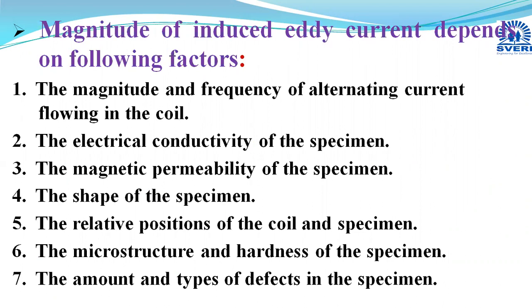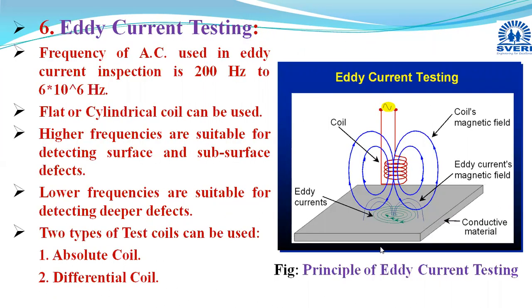You can say that impedance is nothing but the resistance provided to this eddy current. Okay, here eddy currents are generated and they are flowing through this material or this test specimen, and its impedance is measured, which indicates the resistance provided by this material to the flow of eddy current. And depending on that resistance value, we can determine whether any defect is there.